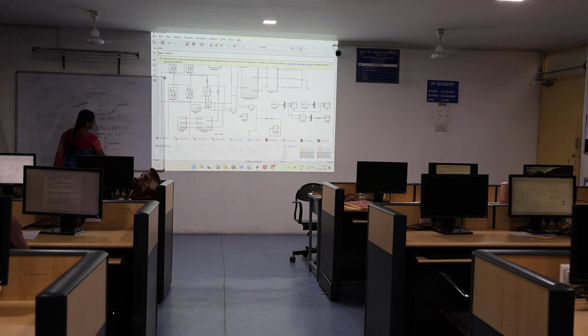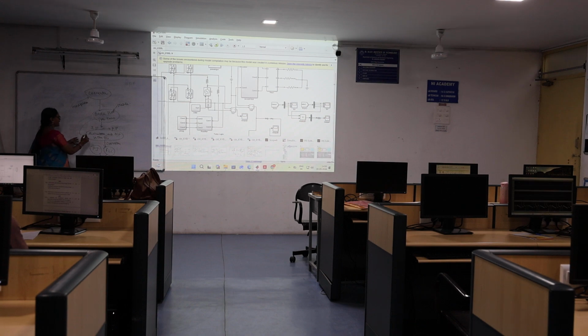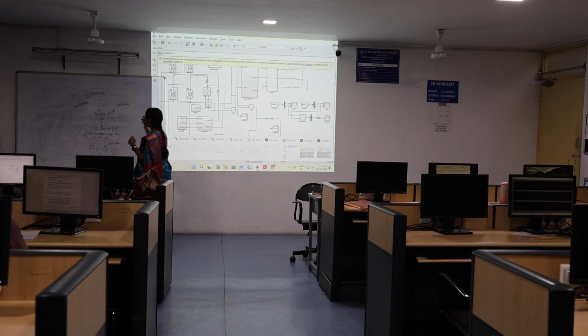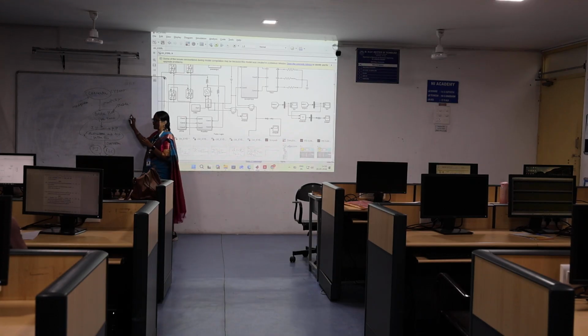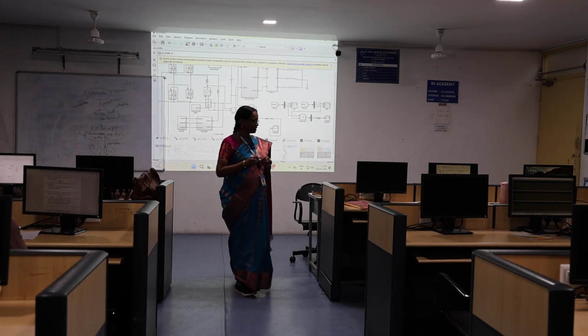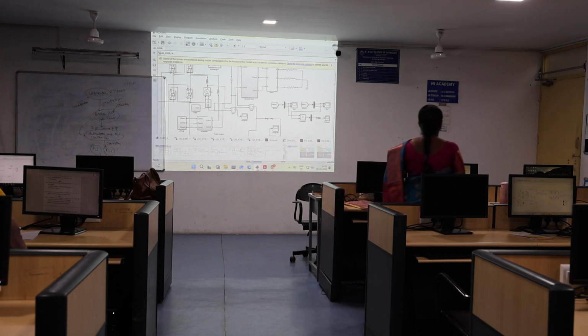So identification is very important in the flow of the converter. Choose one converter and always go step by step. Always give the disturbance, and the disturbance should be reflected in the output. I have chosen the KY boost converter and done the multi-input modification. After that, I ensured from the Bode and pole plots that it is a stable converter. Then we checked with a disturbance in the input and observed it in the output, and then we went for the phenomena. This is the flow, and then automatically you may get the output.